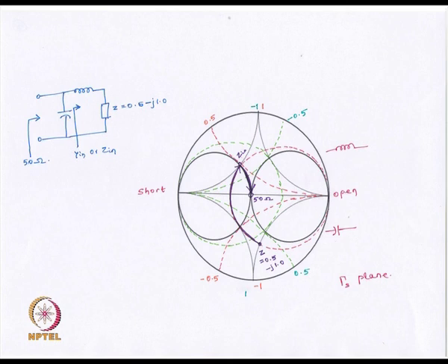Y in, if we consider the Y Smith chart in the ZY Smith chart. And then after that, once we go from here to this point, we have to come back to this point at the origin. So to come back, we need to move in a clockwise direction once again, but then we need to go downwards. To do this, as we have learned earlier, to go downwards, we can use a shunt capacitance. Then this shunt capacitance will move downwards along this constant conductance circle.